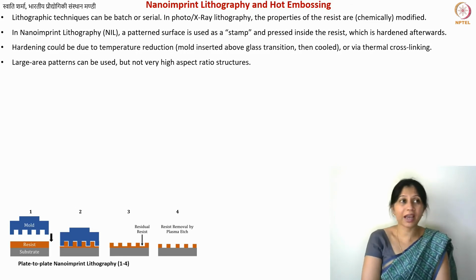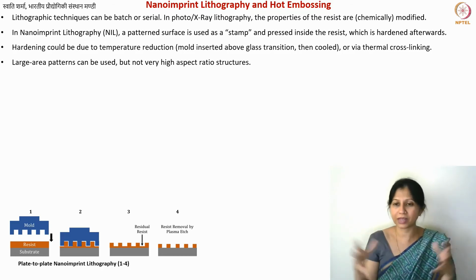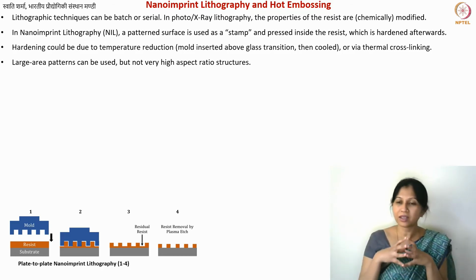Behaving like a glass means it is solidified, and we say glass, not metal or anything else, because polymers are typically amorphous. That is why we say this, because they will have this random cross-linking and so on. However, they will be solidified. Below the glass transition temperature, they will behave like these solid glass-like materials, and we also play with this glass transition temperature during lithographic techniques.